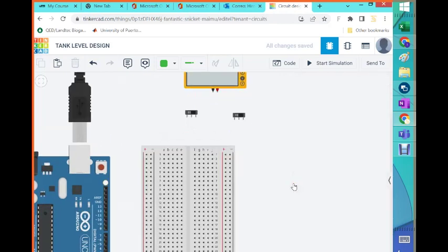So check this out. For example, notice that the switches have a position already. These switches come with a position. Between terminal 1 and the common, that will be in a closed position. That contact is done. So if I use those two, it means my switches are normally closed. But my switches, I said, are normally open. You have to push them to activate them. What that means is that terminal 2 and the common are the ones we're going to be using for our switch design.